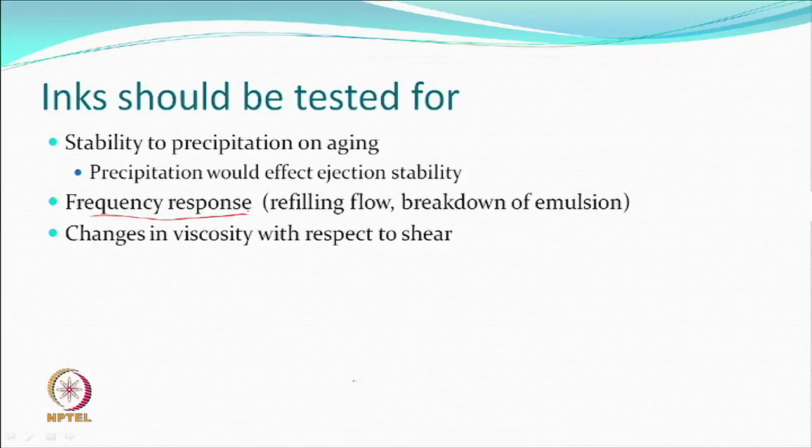When something goes out, something must come in at the same amount. If it does not, if more goes out and less comes in, then you have various kinds of issues. So, it is tested on frequencies of the refilling flow, breakdown of emulsion. Everything is looked at in a static condition, right, but in a dynamic condition it may not be right. Changes in viscosity will happen when you shear. Those kinds of properties may have to be tested. Look, it changes only this much, which is fine for us. If it changes too much, then it may start dripping.